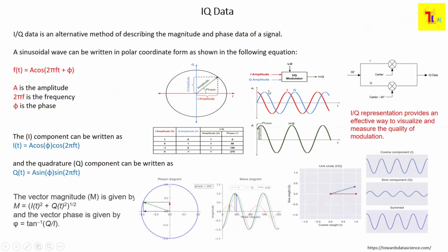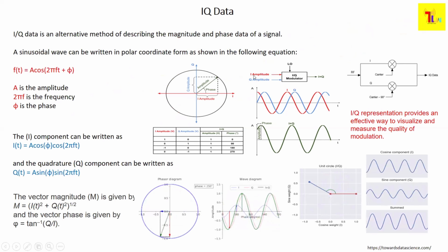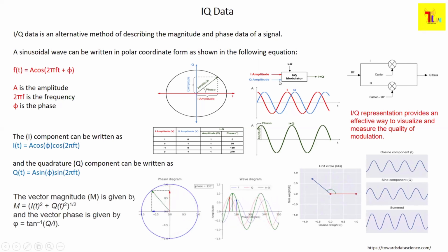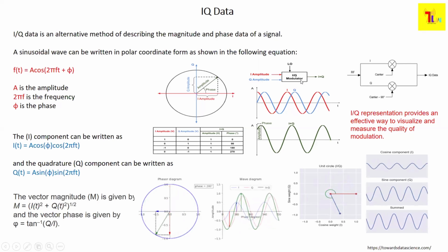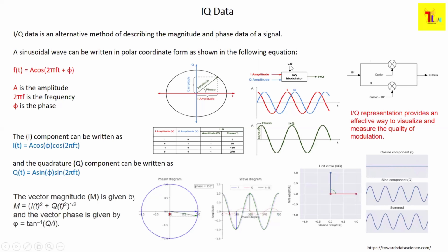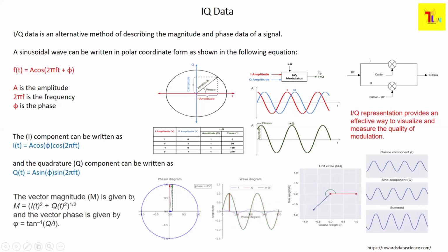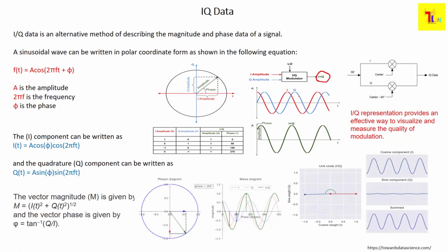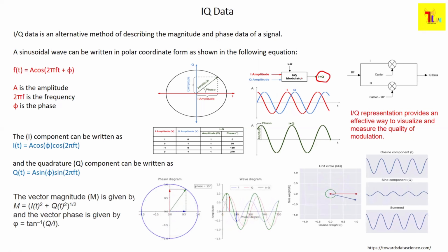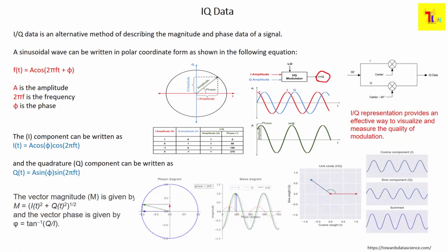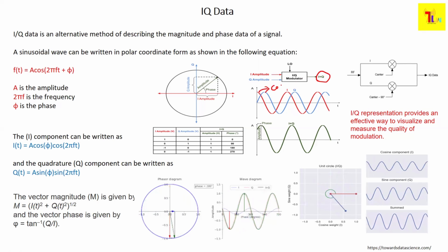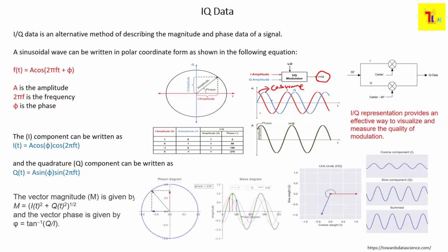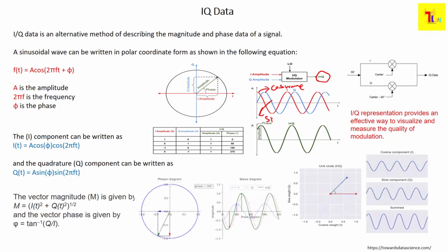So if you go to some basics of modulation, you will be sending one in phase component amplitude and a quadrature phase amplitude, which are fed to an IQ modulator with a local carrier frequency, LO, and that will result in this IQ data, that complete complex IQ symbol. Generally, the I component will be called the cosine wave, whereas Q will be called the sine wave.